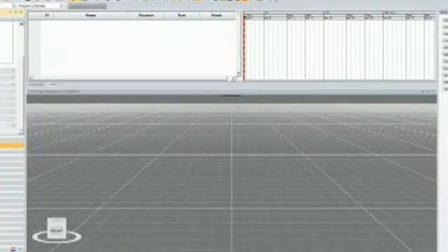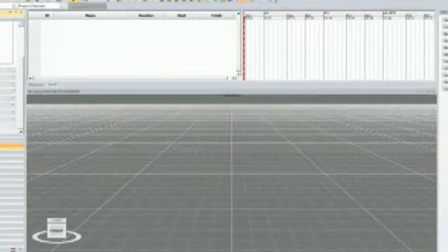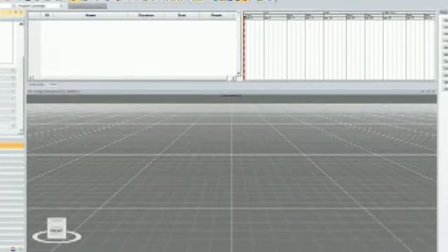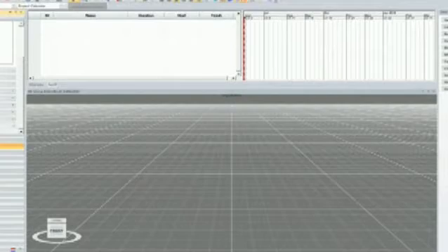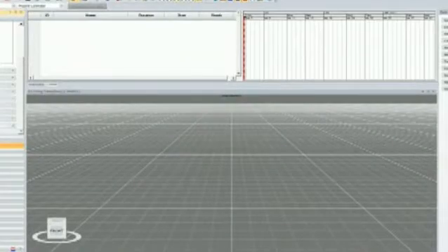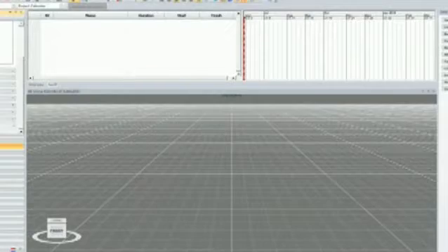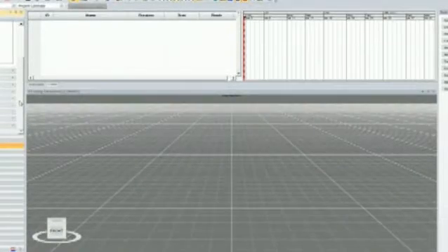So user fields are out of Revit. If you publish a model via DWF, we can take all the parameter data out of Revit and bring it directly into Synchro for that model. So if I click on an object, it'll show me the dimensions of that object, what it's called, location, all those types of things directly out of Revit, okay?